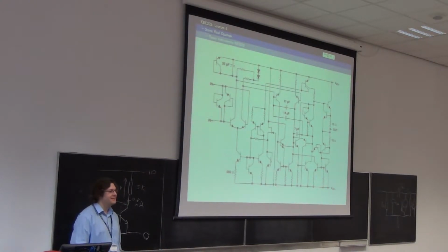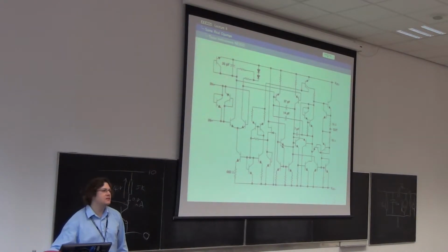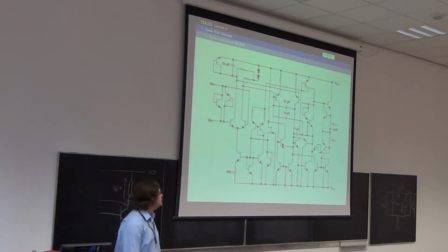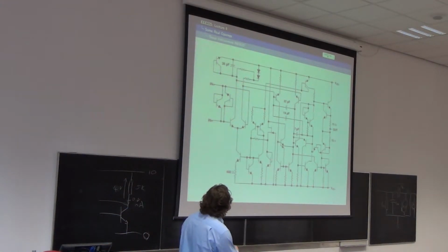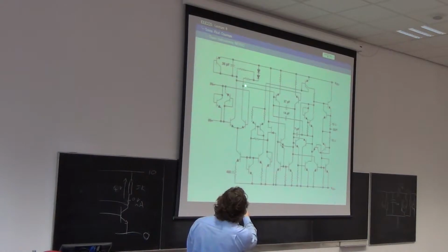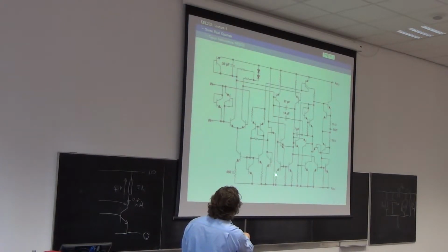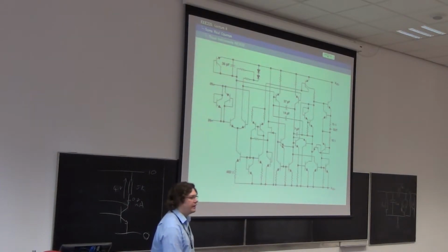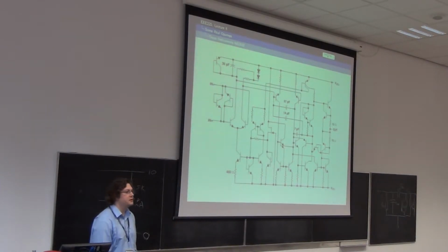It's a trick question. It is there, but you are probably looking for a Darlington or a cascode or something like that. Actually, the clue is, if you look at the differential amplifier with 2 outputs, and these 2 outputs feed these 2 transistors, this business here and that mirror is actually a differential amplifier, and it is the voltage amplifying stage.